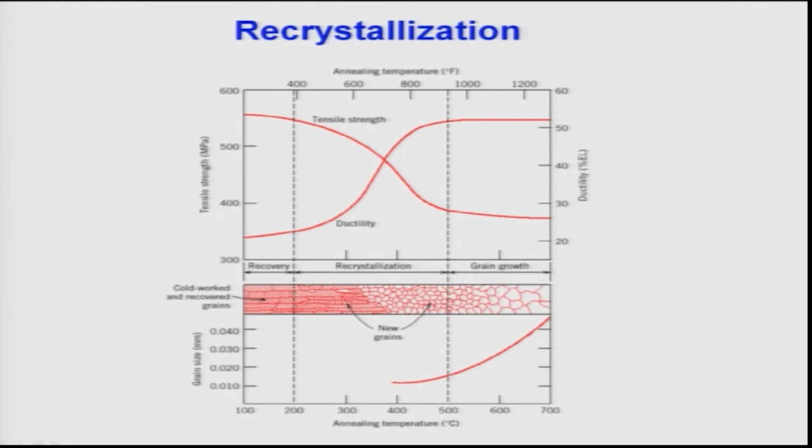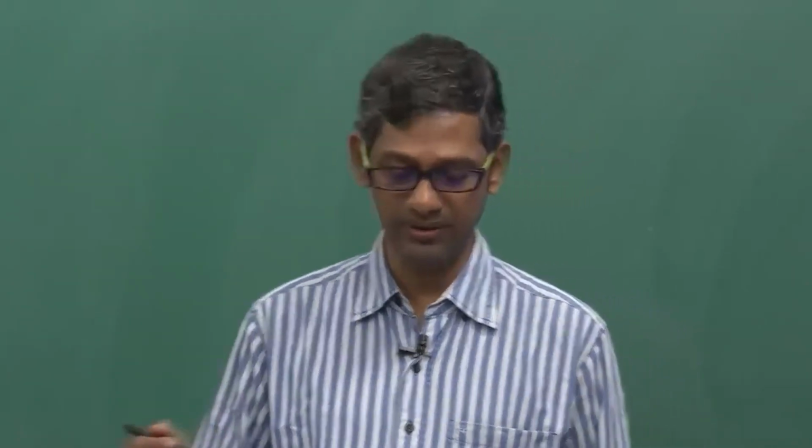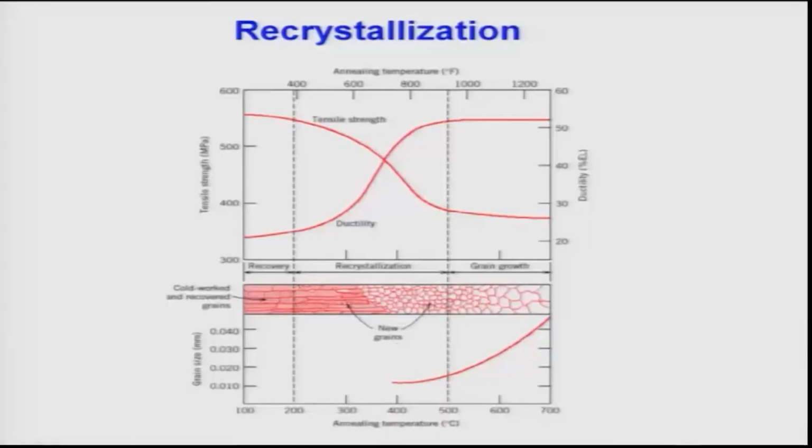They can get annealed out at the grain boundaries, or dislocations can form voids, or arrange by polygonization. At higher temperatures, nucleation of strain-free grains occurs, which is the recrystallization process starting. If you increase the temperature further beyond 0.8, the grains start growing, because that's the way they can again reduce their grain boundary energies.